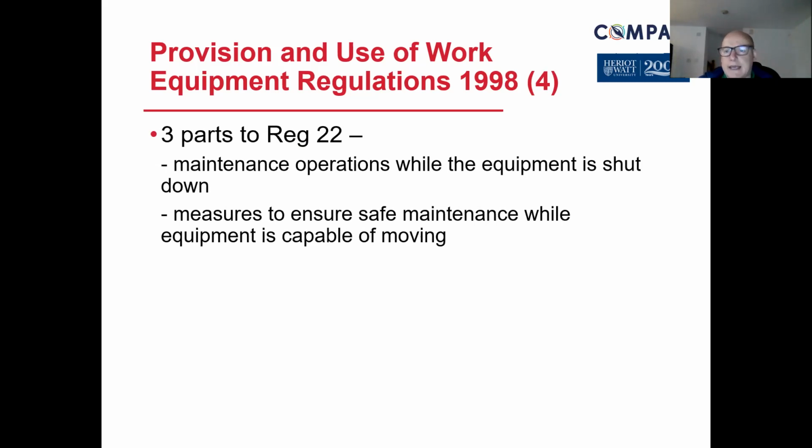So let's say a press, for example, and the press is an impact press, so it can come down. If you lose energy, you would need perhaps a physical restraint, a chock, so that a block of wood perhaps or something else would stop it from coming down and therefore remains in a safe state.